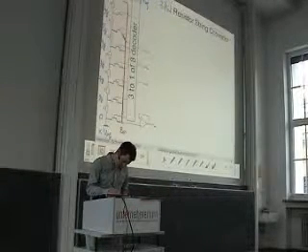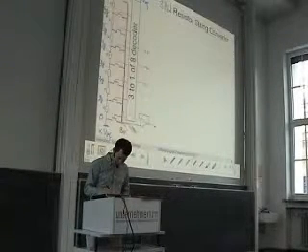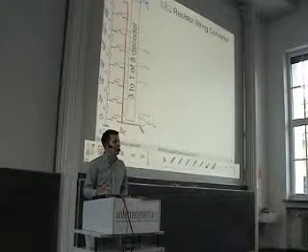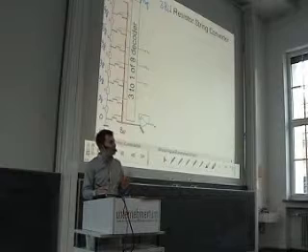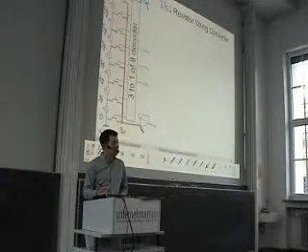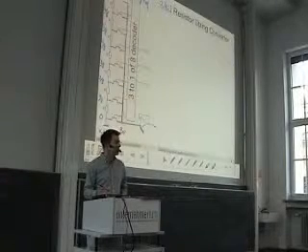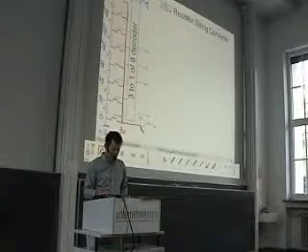And now you can see, of course, in order not to cause a short circuit, it is required that only one switch is conducting at a time. So we have 2 to the power of n switches, but only one is allowed to conduct. So we can also say the control signal is 1-hot coded, because only one signal enables a switch and is active.